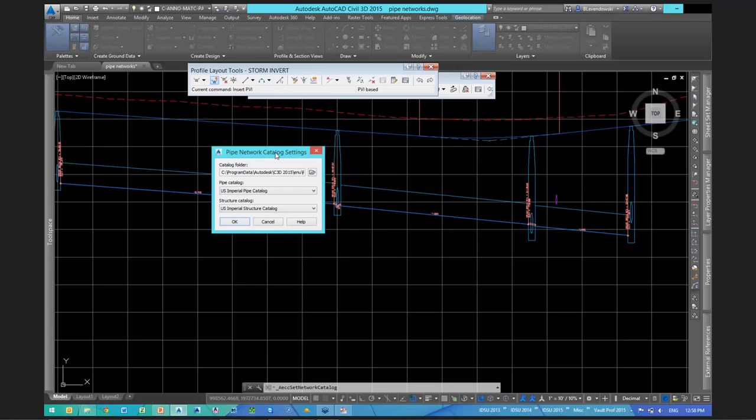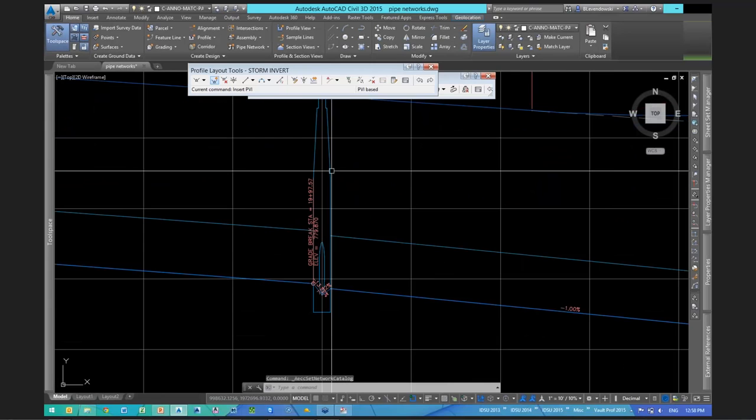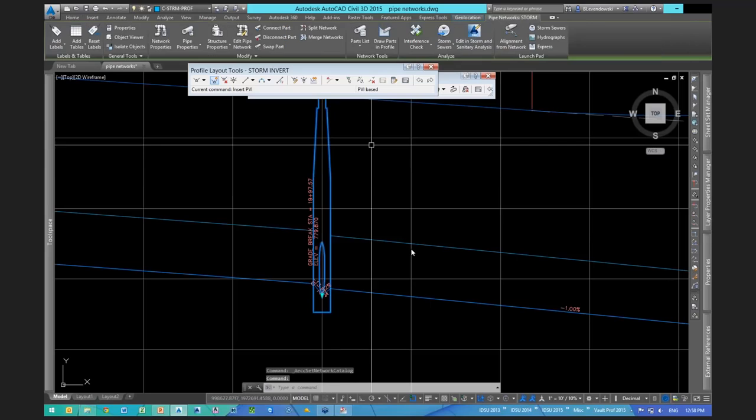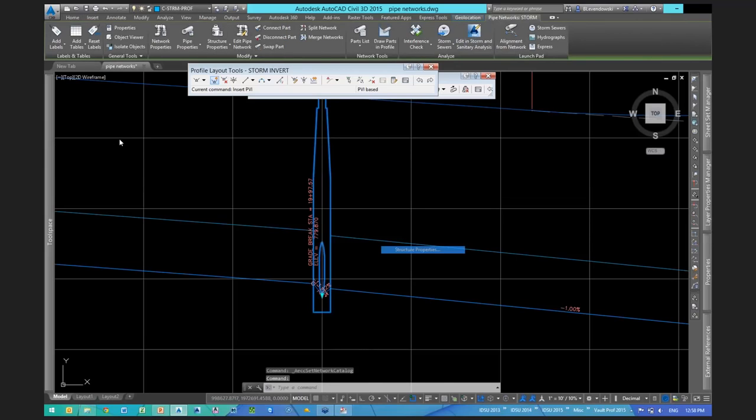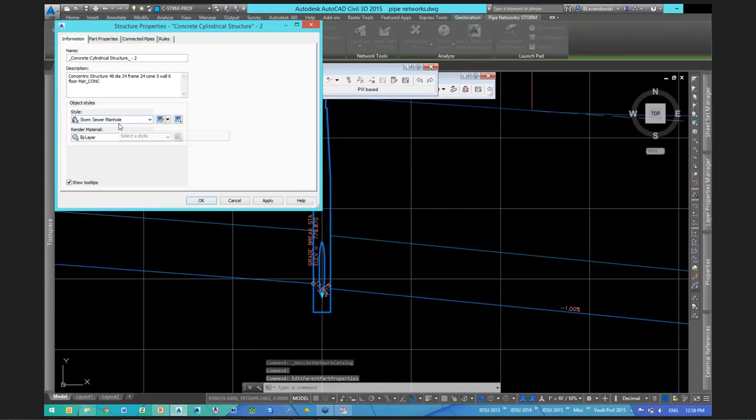As much as possible, you want to be able to swap parts from one item in the parts list to another item, because that parts list is always retrieving from the catalog. When you're making changes, like I said, by just picking on the structure and going to the structure properties, that's not pulling from the catalog, and you want that stuff to pull from the source.